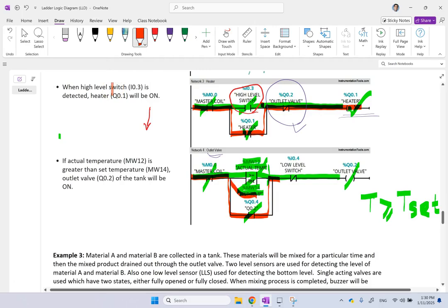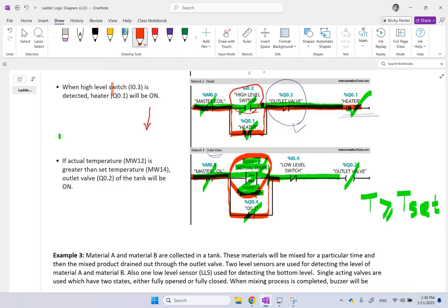Regardless of the temperature that the thermostat or the thermistor is measuring, because during the discharge the temperature can change, it doesn't care about it anymore. Once it reaches there, it opens the discharge valve and it doesn't look at the temperature anymore. It has no effect. Whether it's bigger than or equal to the set value, or because of the discharge the temperature dropped a little bit, it doesn't care anymore.